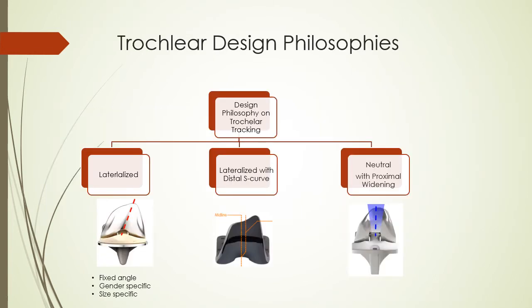Well, there's another design factor on the femoral component. That's the orientation of the flange. And currently we have a couple of design philosophies as well. We have lateralized flange. We have lateralized with a distal S-curve, so it's in general lateralized, but it has an S-shaped curve or tracking on the flange.